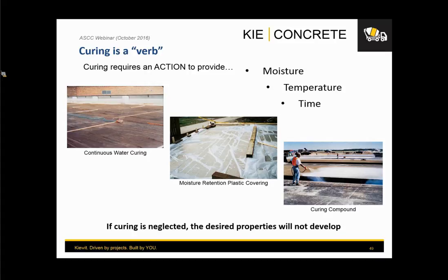Yeah, if you go to ACI 308, ACI 308R talks about the different considerations for curing. I think that's the best practice that I can make reference to. If you go through it, you can see different aspects about curing, the aspects about early curing, which is going to be more on the protection, and then you get into intermediate curing and final curing, and what the methods are and the reasoning behind it. I think that will be the best document that you can look at.